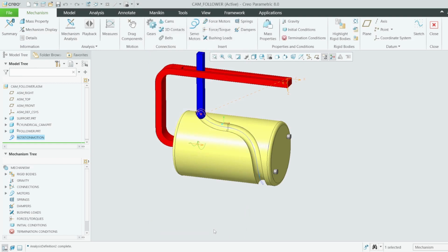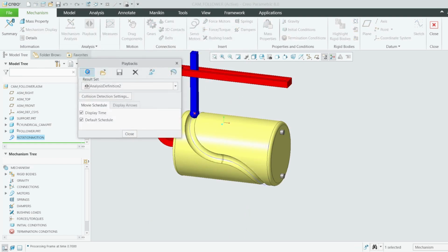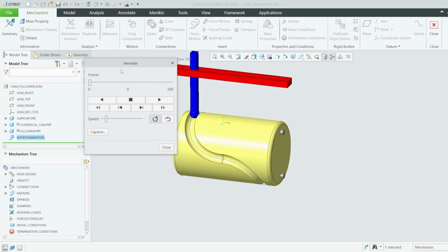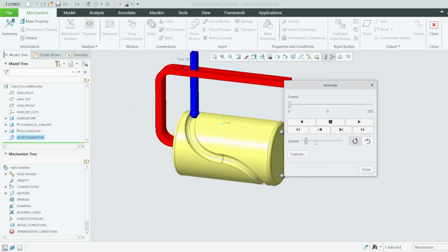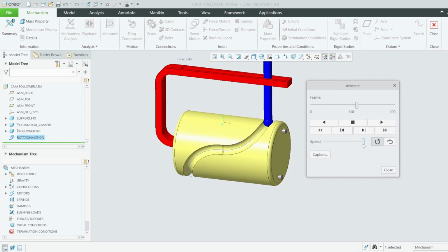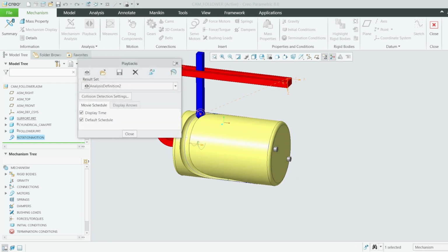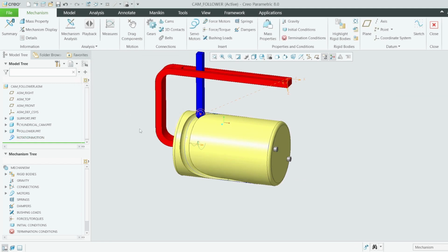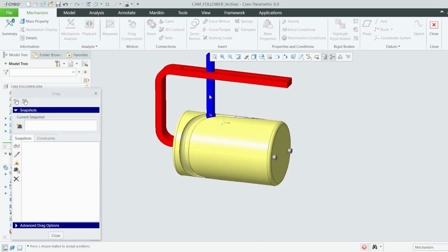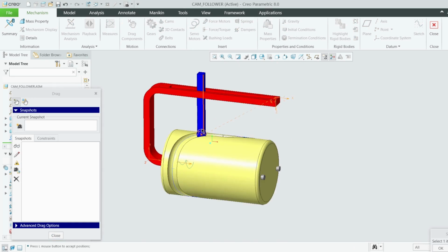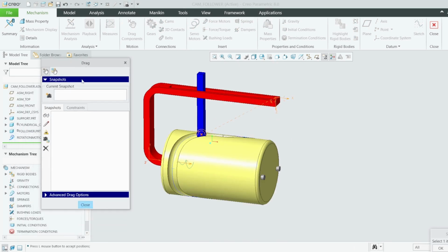Like that. If you go to the playback and you play, let's do high speed, let's play. Okay, you can see the simulation here. Let me first close this one. Maybe let me move this one here somewhere there. Assuming I want my analysis to start from that point, you can create what we call a snapshot and select here snapshot and call it start.